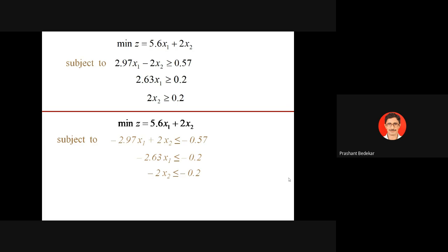After this, I will simply apply the linprog function, and with that function I get the solution: time multiplier setting of relay 1 is 0.2592 and that of relay 2 comes out to be 0.1. Remember, when I say 0.2592 is the time multiplier setting of relay 1, I am considering that the relay is a numerical relay.